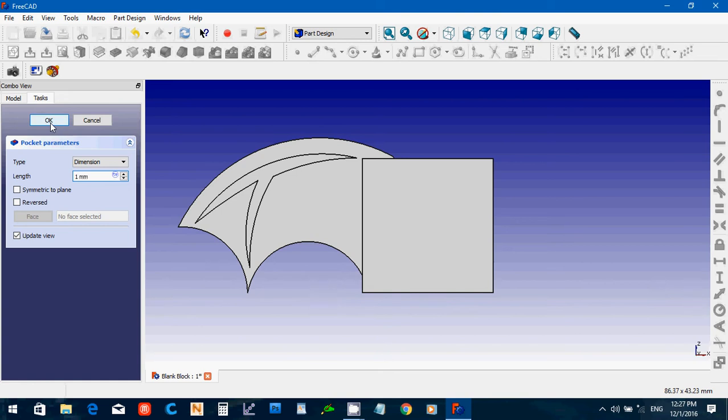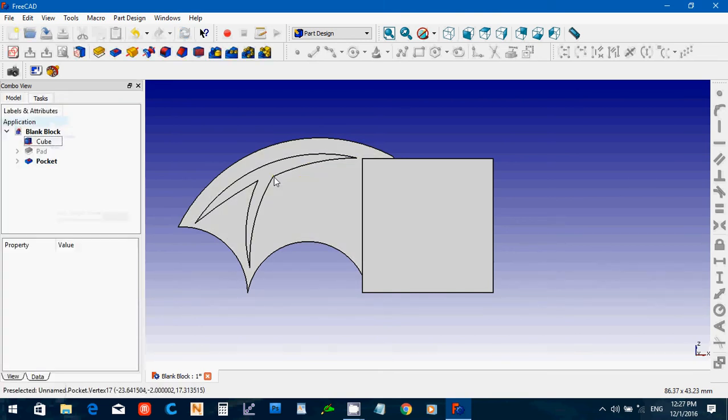Now, the tricky part, I could extrude that out, the 1 millimeter, but then it's going to have to probably have supports, so it would have to print all the way up to where that extruded out area is, which will create a lot more material. Now this is going to create a hole where supports go in. It's going to have to go in that hole and be dug out later.